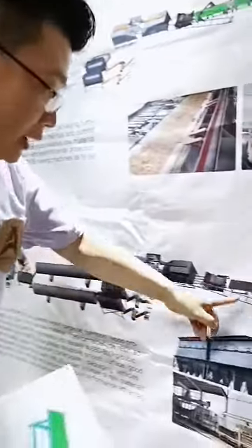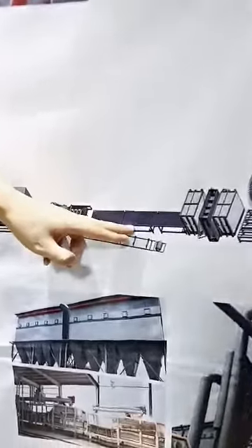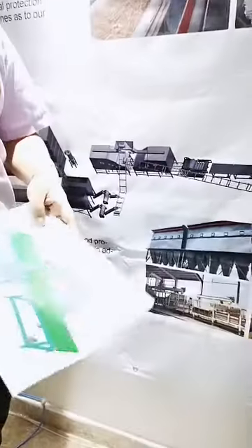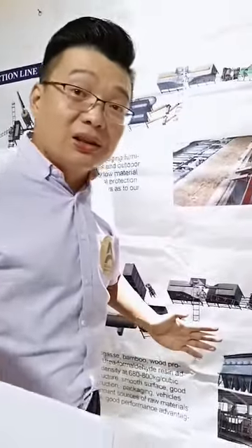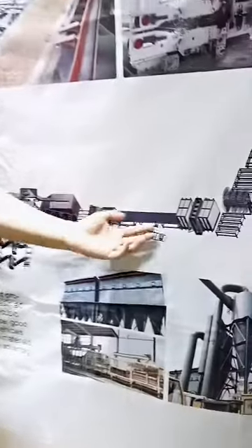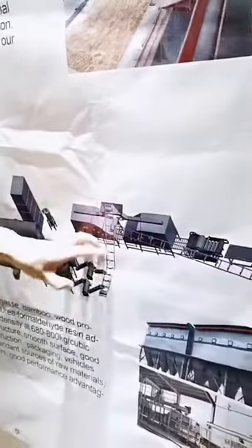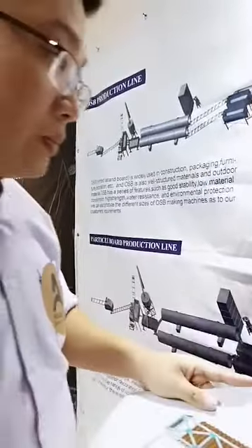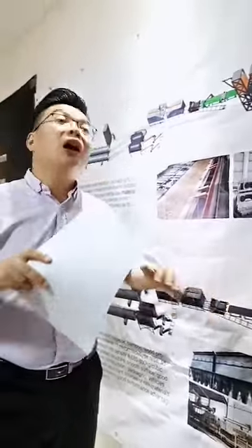Okay, we also have trimming saws on both sides of the belt. Here there is a trimming saw for the primary trimming of the edges, to cut off some offcuts. You can see the cut-offs are transferred by belt conveyor to the silo. Because this is just with some glue and not yet pressed, it is easier to reuse. It goes to the glue blender, which mixes it with the glue again. So now, after edge trimming, cross trimming, and the electric scale.